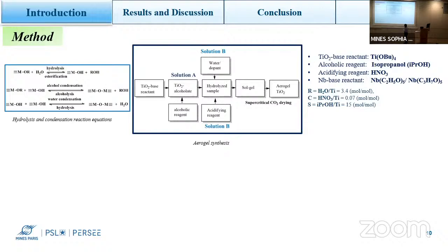We chose this temperature because at this temperature we can get a good crystal structure. At the same time, it's not too high to obtain rutile, and we can also get a good anatase structure. If the temperature is lower, like 500 or 400, the crystallinity is not good enough. But if it's too high, we get a mixture of rutile and anatase phases.